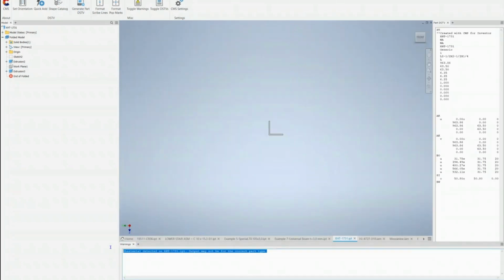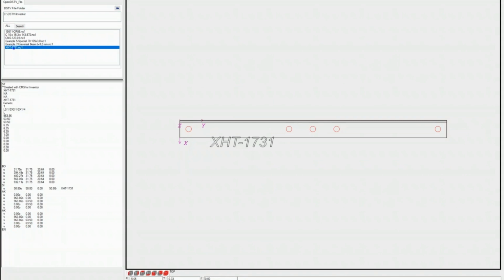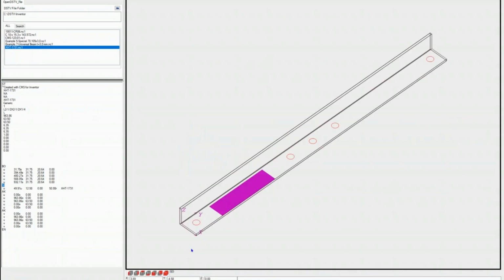The software actually detects that it's sheet metal. It gives you a warning: hey, this is sheet metal, but you created it as a part, so just watch out. It's a warning, not necessarily an error. If I try to see that NC1 file on my viewer, I copy that and refresh one more time. As you see, this is a stamping that has been coming outside. Even on the NC1 editor, you can reposition them as well. Okay, and here you go.